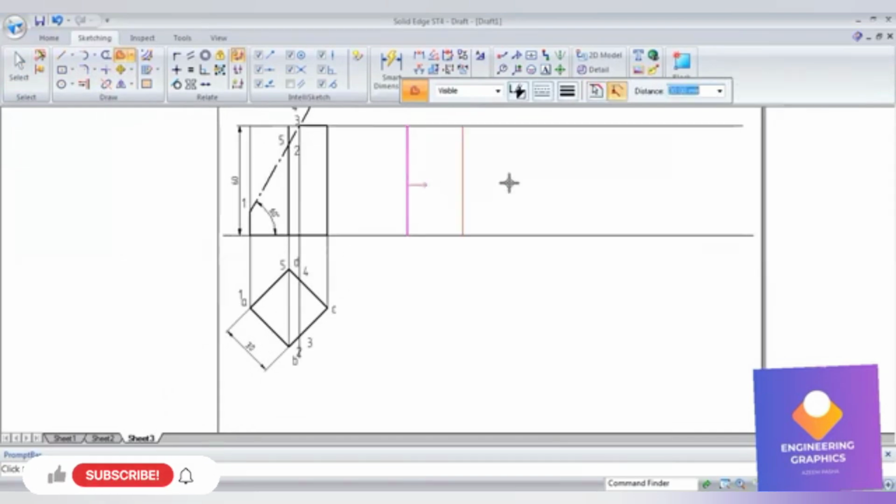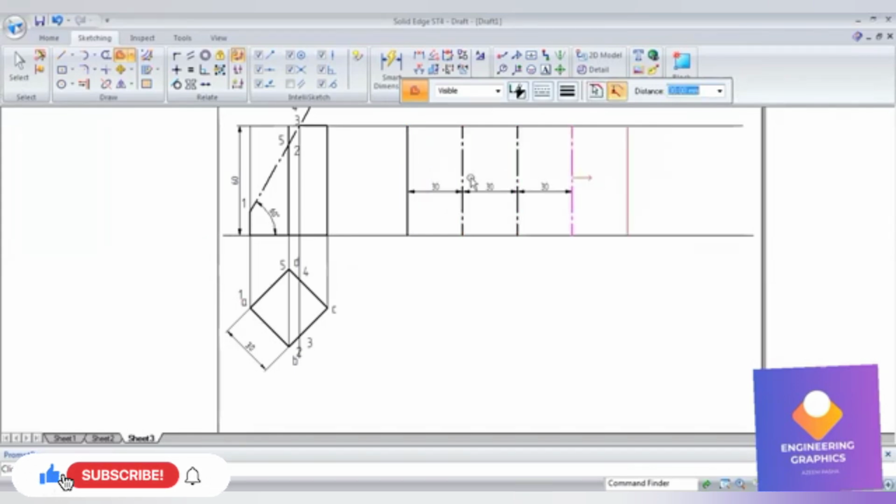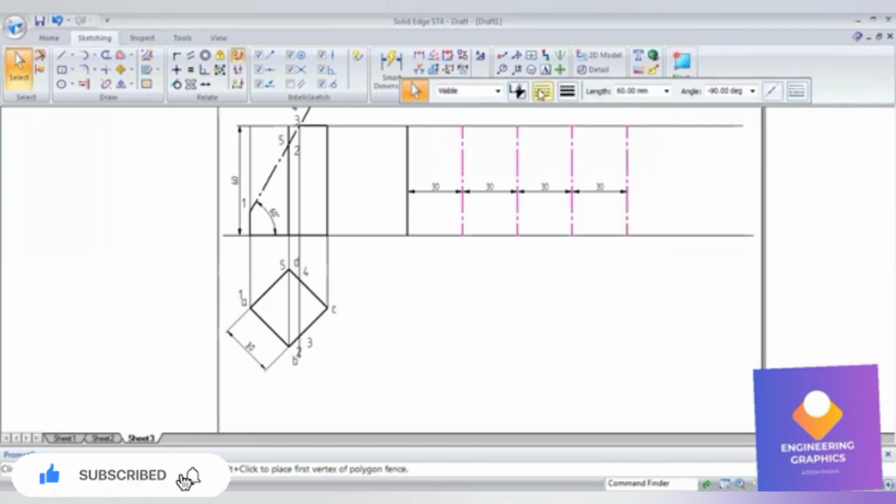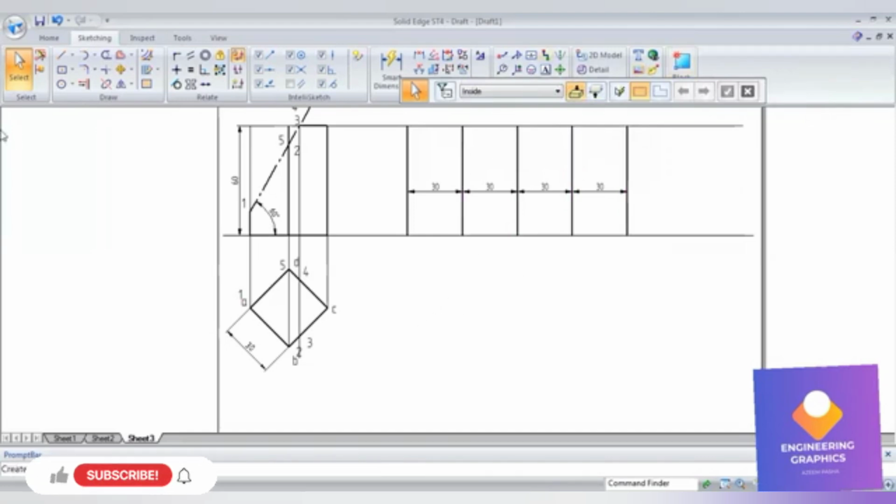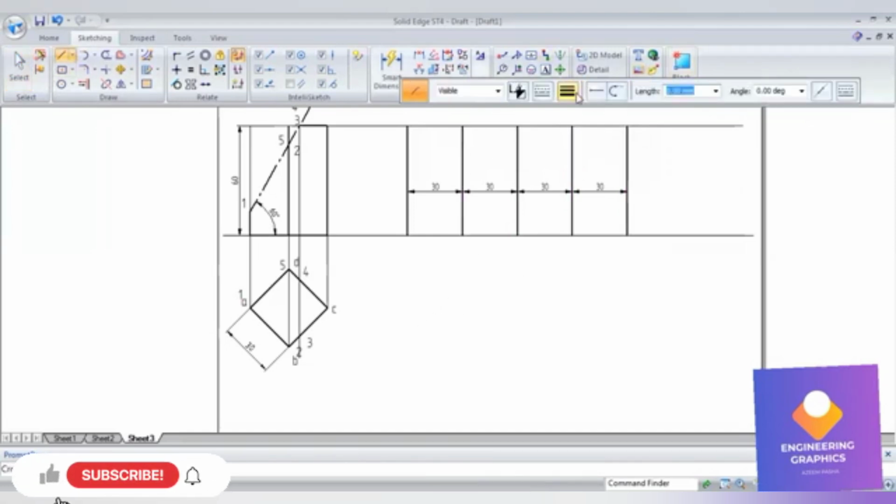Okay, now here you can see the dimension, it is 30. Totally there are 4 faces in the square prism. So using the offset command, I will be giving the distance of 30, and then I will click 4 times. Okay, I will get the 4 faces here. I will make all these lines continuous.